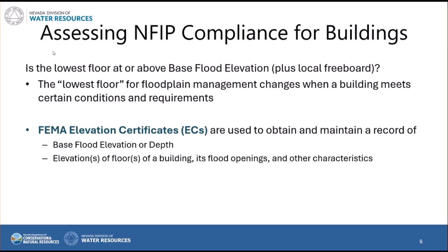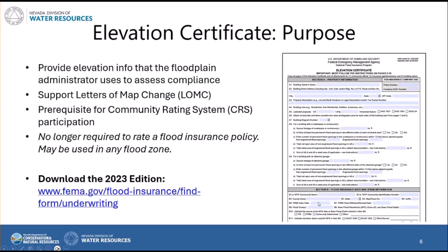But the FEMA Elevation Certificate is a form that's designed specifically to capture the kind of information that you're going to need, including the base flood elevation or depth at a site, the elevation of floor or multiple floors of a building, information about flood openings, attached garages, and other characteristics. So that's why we're going to talk about the elevation certificate today.